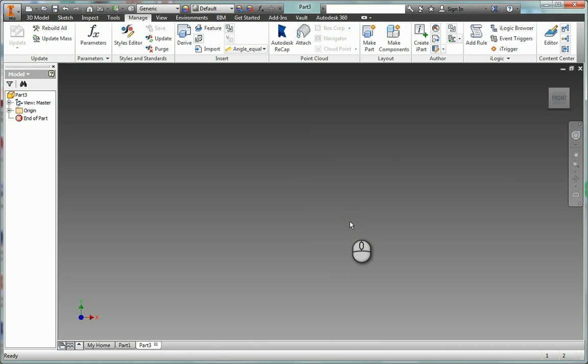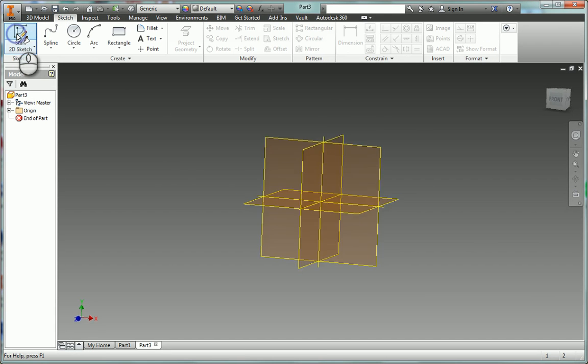If you have your homework assignment, you're going to see the different dimensions and the equations we're going to use for those dimensions. The point of parametric modeling is that if you get done and you want to resize the entire part, you can do that just by changing one dimension, and everything else will be based off of that dimension algebraically. It'd be really nice to be able to shrink the entire part down by changing one dimension. So we're going to start by going back to sketch.